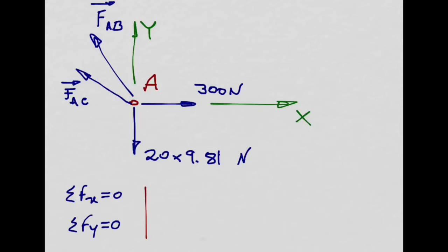And we have all the forces acting on point A. So this is the free body diagram of particle A. Now we can start adding all these vectors together. So I'm going to start with this 300 newtons. This force vector here, I'm going to add it here. So we have only a component in the horizontal x direction, agree with me? So this 300 newtons only has a component in the horizontal direction.